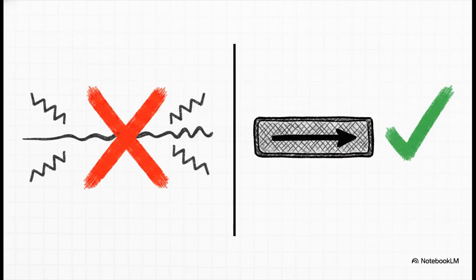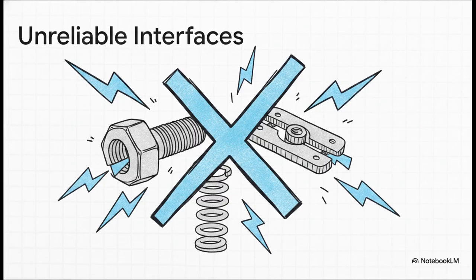A thin wire adds massive amounts of inductance at high frequencies, which creates wild resonances. In fact, at RF, a poor bond effectively becomes an open circuit. It secretly turns a beautifully designed but improperly bonded enclosure into an antenna that's just actively radiating EMI everywhere. To stop this, braided bonding straps with that wide, flat geometry are absolutely essential. Interestingly enough, knowing what not to use for bonding is just as critical. Never, ever rely on mechanical interfaces like shock mounts, nut-bolt contacts, or movable joints for your RF bonding.